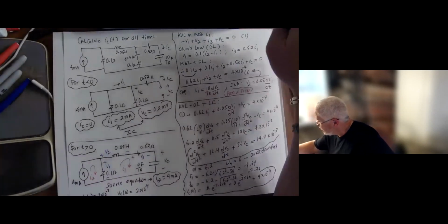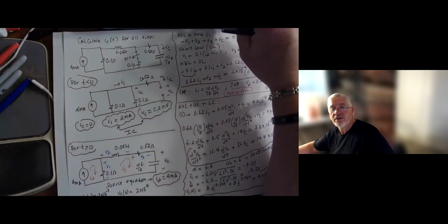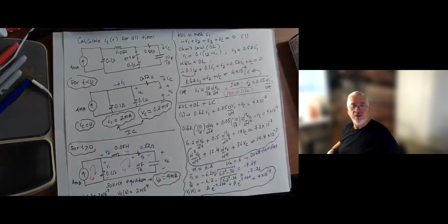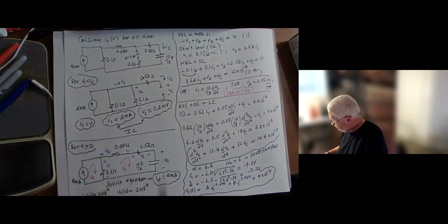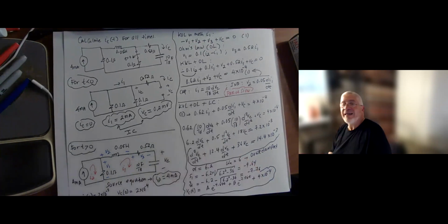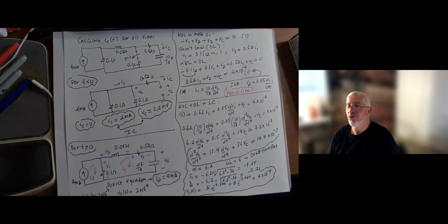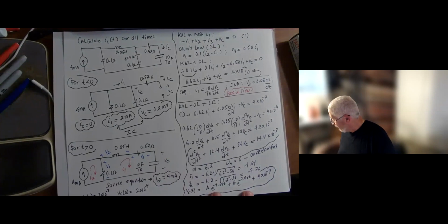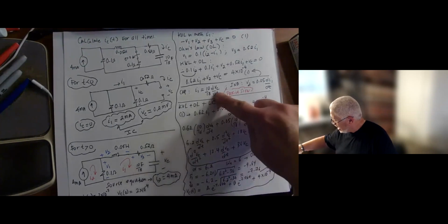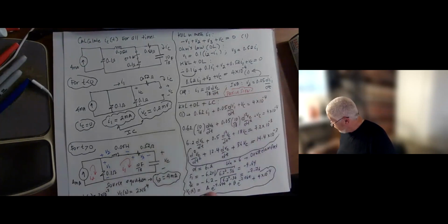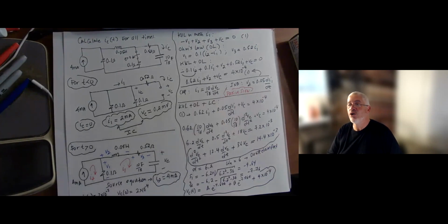Okay, let me see if I can do a little bit of zoom here. No. Okay, so these are the two initial conditions that we would have that would give us equations for A and B. I think I've done enough to get you going. I'm hoping that last step, your differential equation course and basic algebra helps you get there. But this general solution is a great step. You would need to get I1 by taking the derivative of this and multiplying it by 10/18 and then enforce this. That gives you two equations, two unknowns for you to work with. I hope that helps.